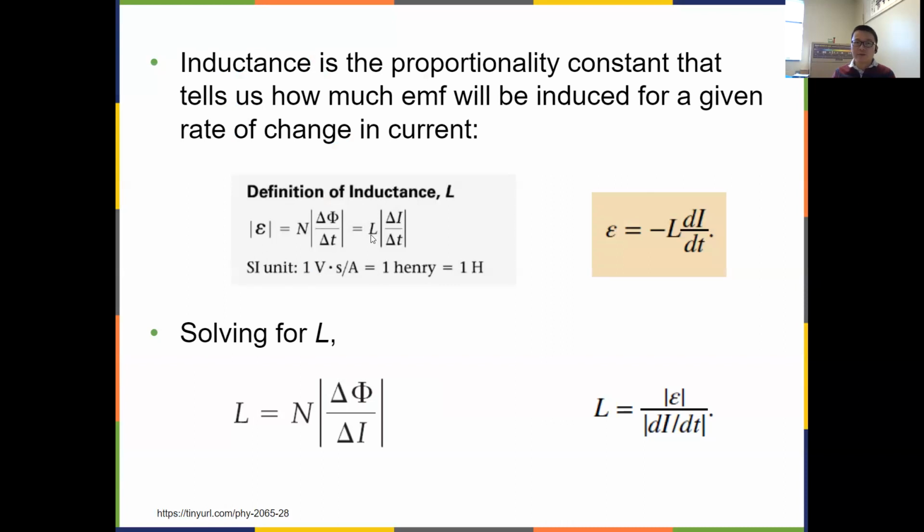So here we introduce the definition for the inductance of the coil, which is calculated by the induced EMF divided by the change of current over time t. So L equals, you can start from this relationship, take the second turn and the third turn, set them equal to each other, and rearrange the terms.